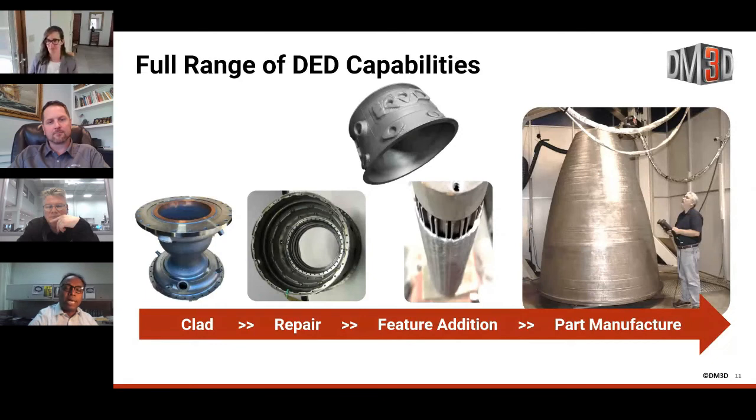Copper extracts the heat, gets a better cycle time for the toolings, but steel gives the durability of the tool. So we have done a lot of those. But what you just said, stellite application, we have done some of those for actually a tooling for ultrasonic AM processes. They have these toolings and those are wearing out. So we applied stellite on steel for those toolings.